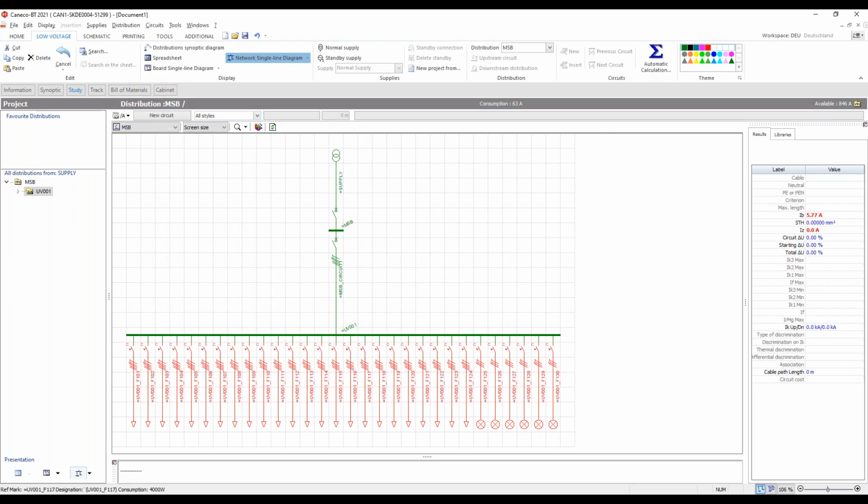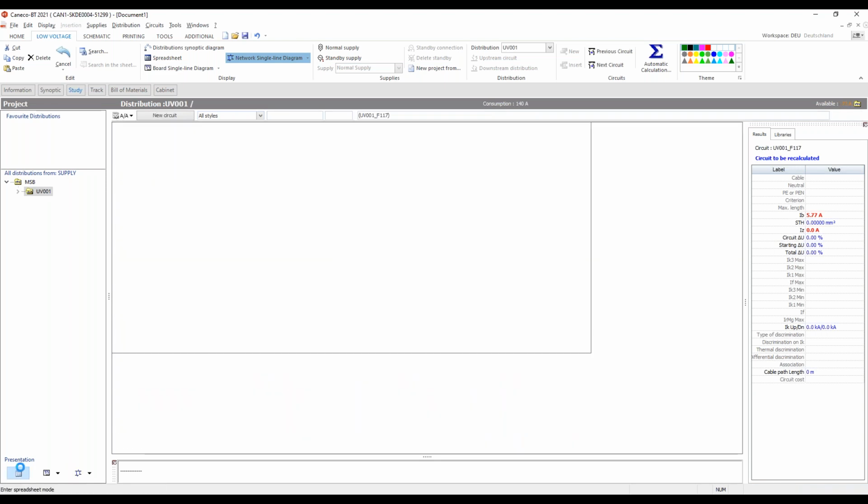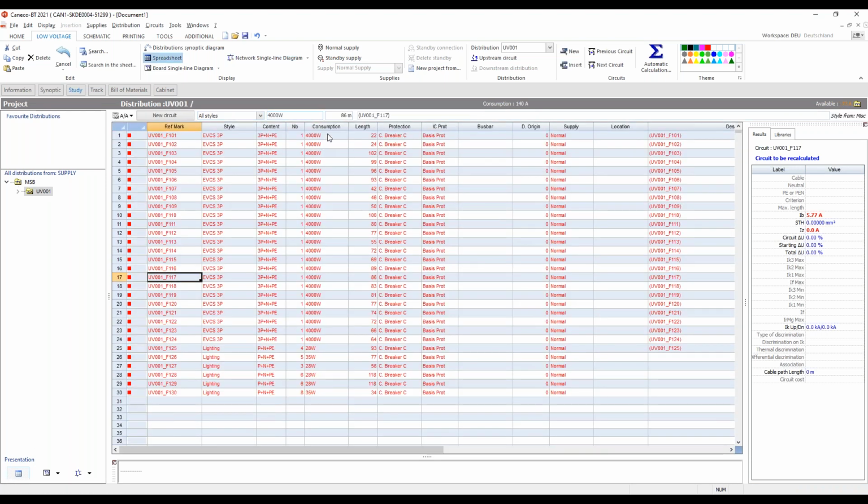And now we can just calculate everything which is behind there. For option number 1, we maybe have to adjust the power. So you see, as I told before, we started with 4000 watt. Usually a 24 charger is quite a lot, but we will still define it with 11 kilowatt because it's a common charger. I think 22 or more is not really useful for such a project.